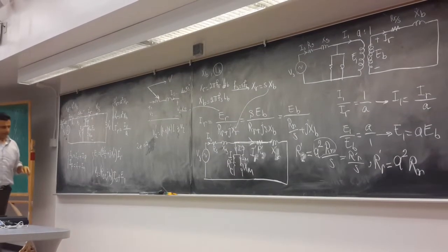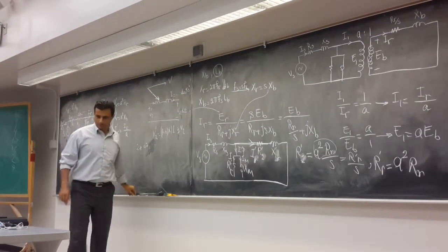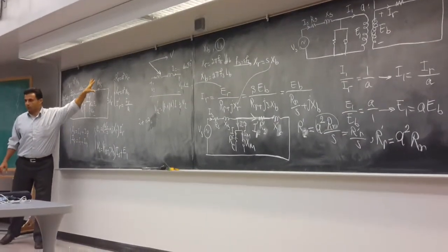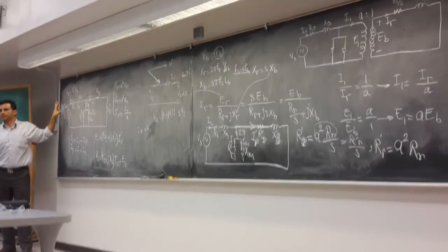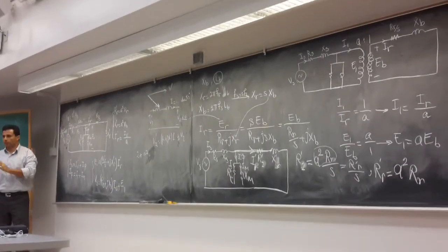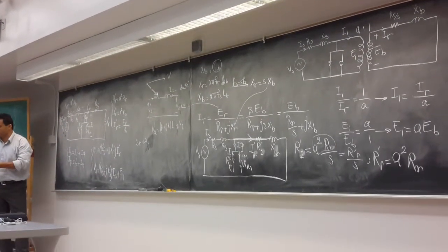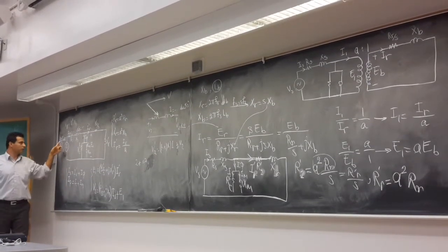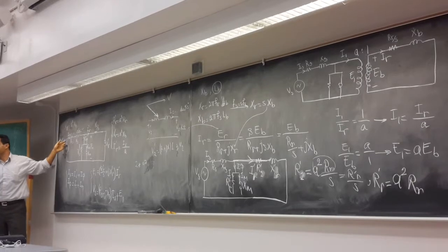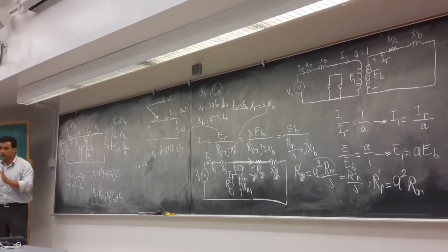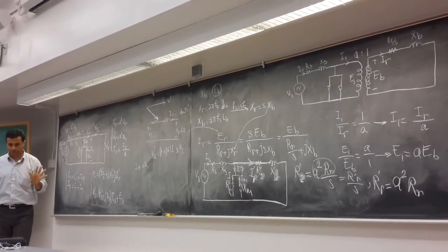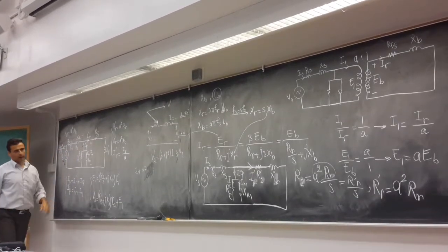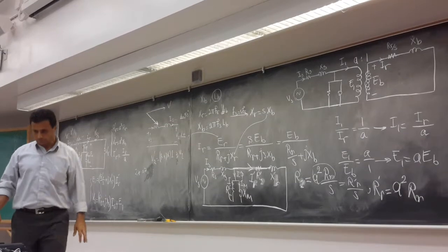Okay. So this is the equivalent circuit of phase A. I'm talking only about phase A; usually I select phase A. Again, if you want to solve phase C, go solve phase C. The problem is you're going to end up with minus 240. I'm going to go with phase A because I usually select my phase A as 0. That's the easiest one for calculation, just for calculation, nothing else. This is the equivalent circuit of phase A for the induction machine.